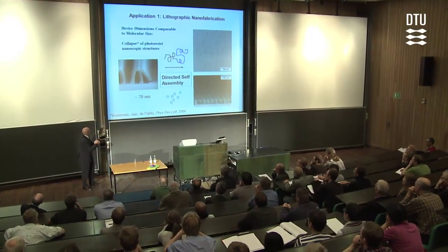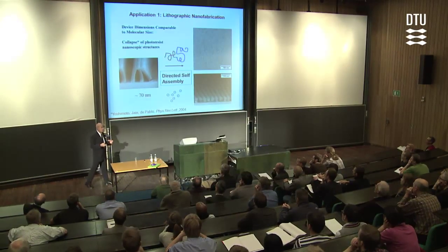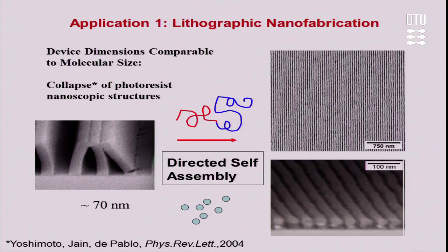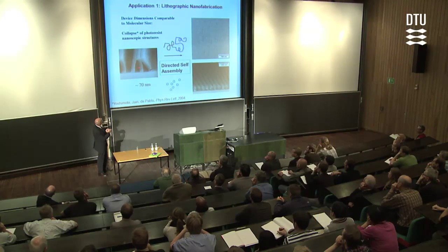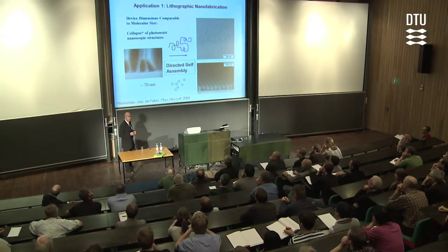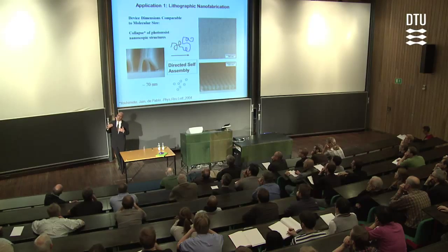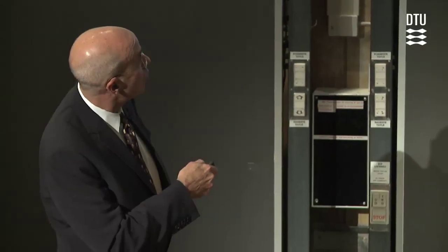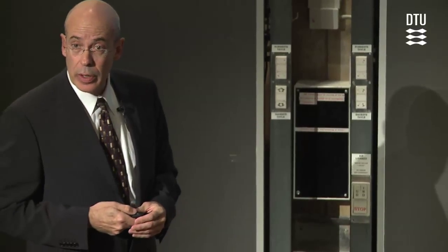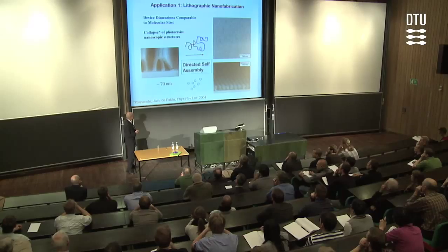So in this picture, you have walls created with PMMA, polymethyl methacrylate, so it's a polymer that at room temperature should be a glass, very, very stiff. You take the same polymer and you make it a thin wall, and you see that it actually bends, it flows, and it cracks. So this would be useless for lithography processes. Turns out that this collapse of photoresist structures is becoming one of the major roadblocks for this industry to go to smaller devices and higher densities. So this industry really needs to overcome this problem and come up with alternatives. Otherwise, we're stuck with the current speeds.